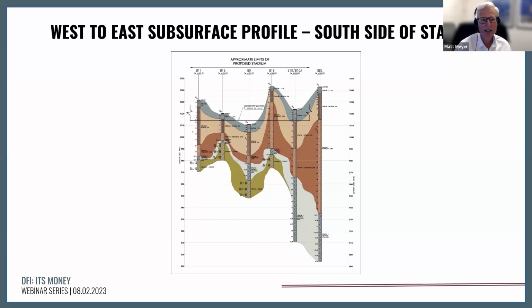They have higher CPT tip resistances. They retain the relic rock fabric of the underlying subsurface materials, and they are typically a little bit more granular than the residuum. The residuum is on the border of essentially an SM to an ML. At this site, a little bit more on the SM side of things than the ML.